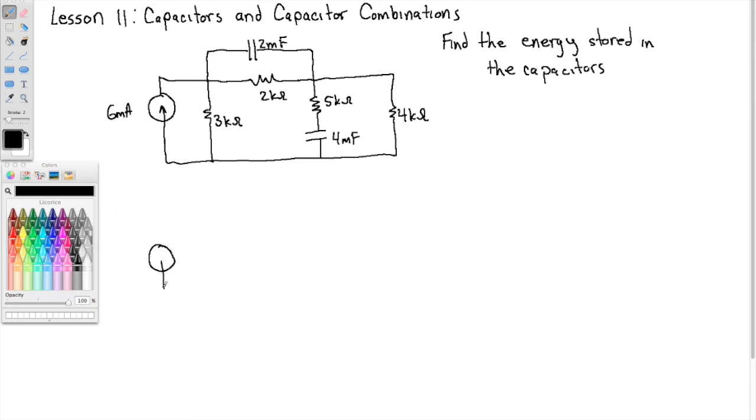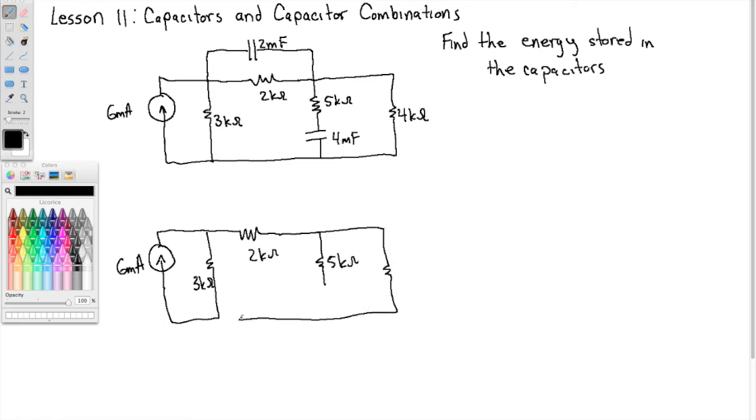So at DC, the capacitors we can model as open circuits. No current goes through them. So let me replace the capacitors with open circuits. I'll draw that in blue. Here's the new part of this. And I say the new part because now it's essentially a problem from the first 10 weeks or so of the course. Right?